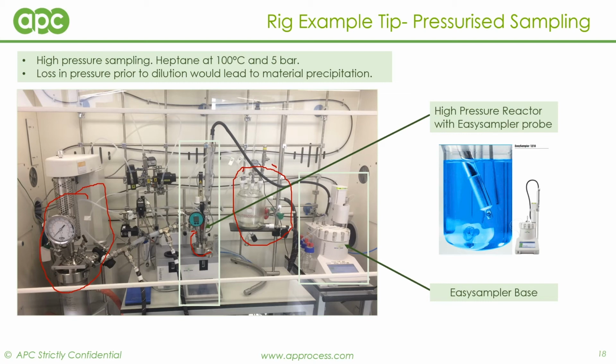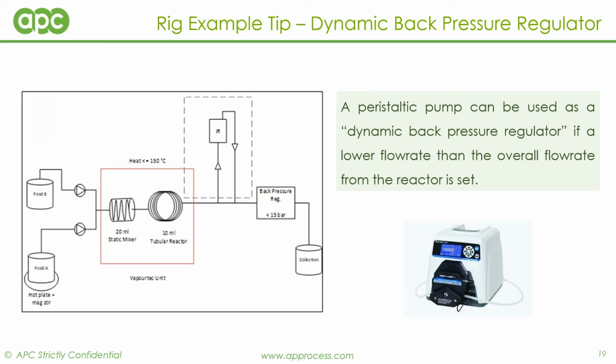If we were operating in a traditional batch unit operation of this nature, offline sampling is next to impossible due to the high pressure nature of this system. Generally what would happen is that the extraction would occur and it would immediately then be either moved into a separate vessel or the crystallization would happen in the same vessel, therefore impossible to get that information. Therefore, not only will this flow process increase the throughput, it will also add data intensification and understanding to the process.